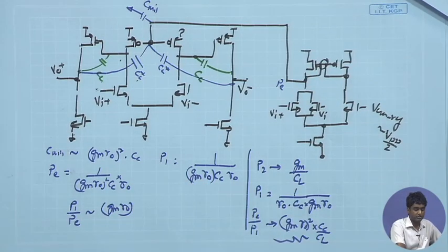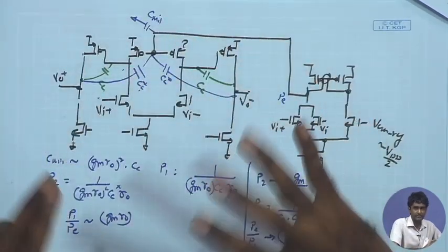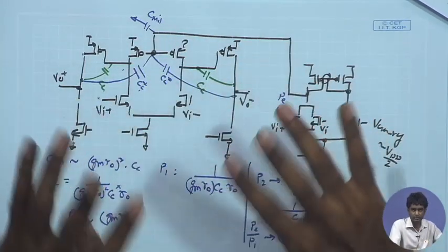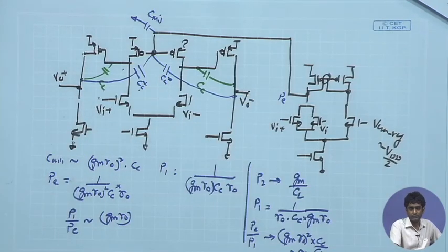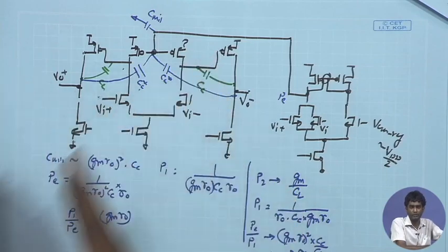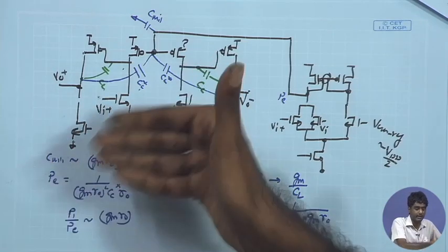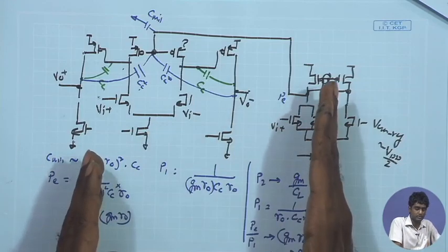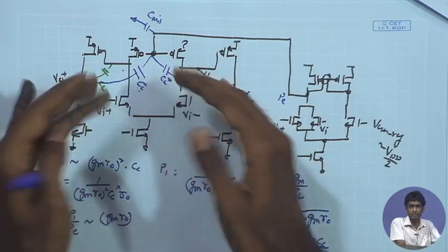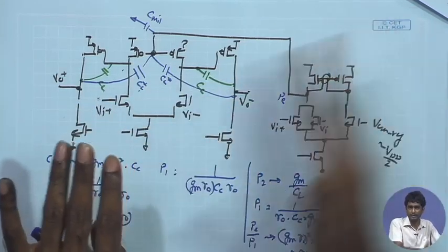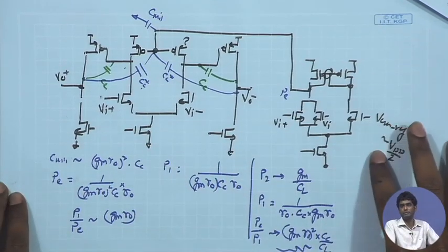So in the simulation exercises, apart from following the steps that have been suggested, you have to go one step further and try to think about the problem at hand a little bit more deeply, whether it is just DC biasing, whether it is frequency response, whether it is noise analysis. So another exercise on noise analysis also has been suggested, where you have to size the transistor appropriately so that the 1/f noise corner is pushed towards lower frequency, and then you have to make sure that the bandwidth of the differential amplifier for the differential operation along with the CC compensation is sufficiently higher than the 1/f corner frequency. So that is another interesting example you can look at.